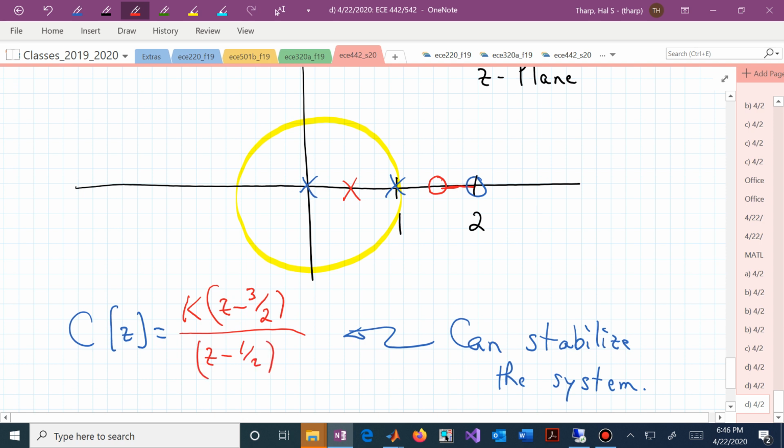what's the root locus now? Now we know that we have that segment and we have this segment. So that we start at the poles. These two actually break away and will leave and go into or outside the stability region and eventually approach those finite zeros. And this now says that as long as we crank up the gain only enough to get us to that box, we will remain stable as long as that box hopefully has the third pole inside the unit circle.